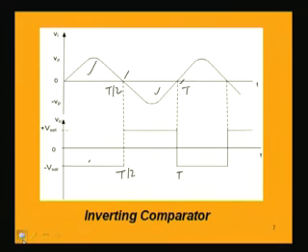And if we now see this circuit, although it is giving a perfect square wave, there may be one situation where it is misidentifying zero crossing for a noise. That means, if noise voltage is present, when the noise voltage also crosses 0, that can also be detected as a zero crossing for this circuit. So, that is one disadvantage basically.